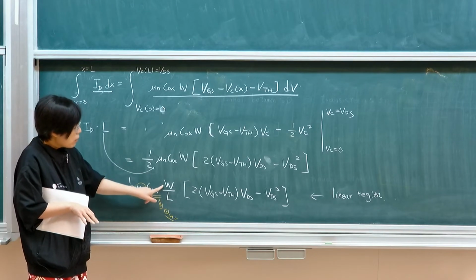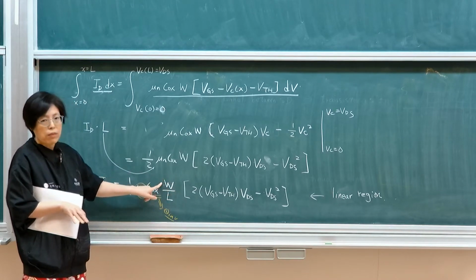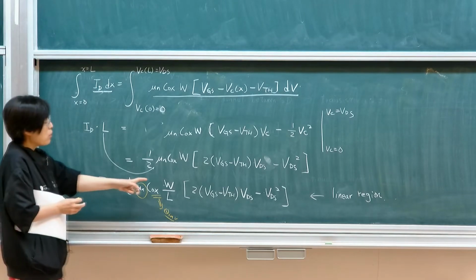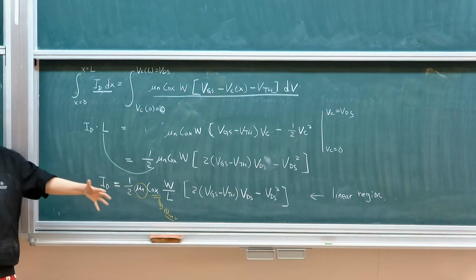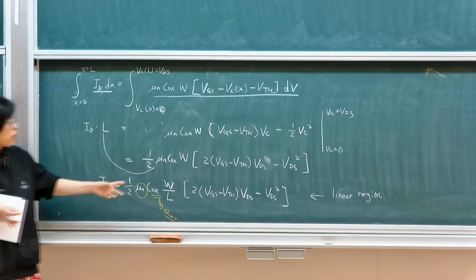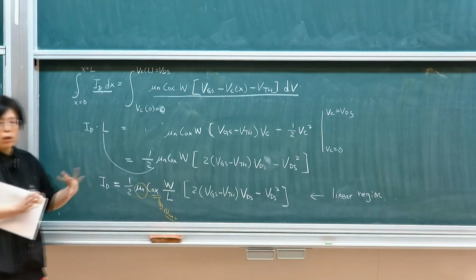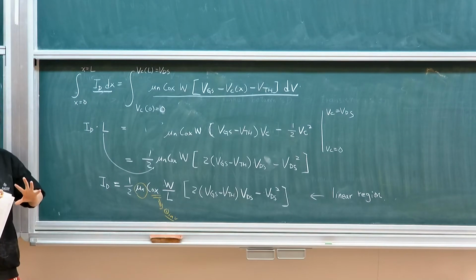The width of the transistor is similar to the cross-sectional area for a BJT. BJT depends on the cross-sectional area. In this type of device, it depends on the width of the channel. The wider the channel, the more current. So current will be the same as the cross-sectional area in a bulk device. We call the bulk devices like the pipe.